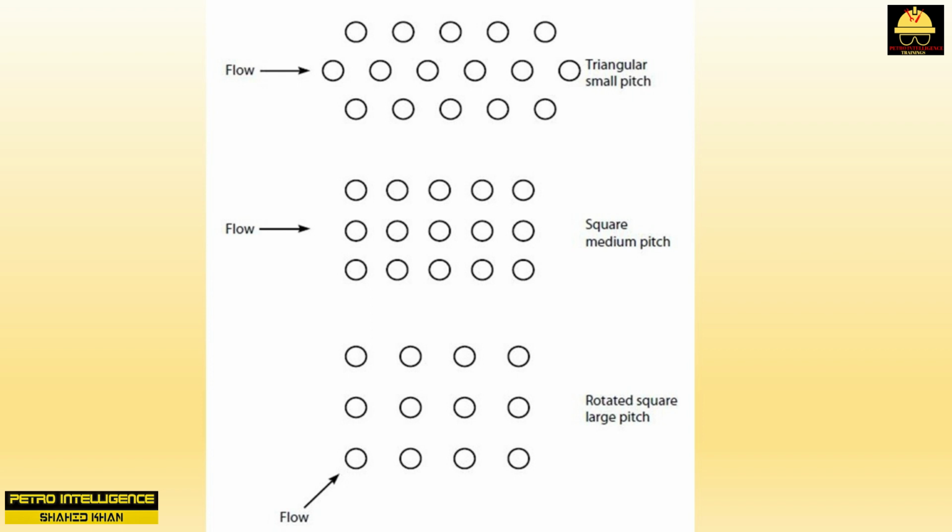But this time, the arrangement is a square pattern. This pattern reduces the number of tubes in a shell of a fixed ID. Also, less turbulence is created by the tubes. Some fluid may flow between the tubes without encountering the tubes at all. All this reduces heat transfer efficiency. But hydroblasting between the tubes is usually possible, depending on the extent of tube bending and twisting.